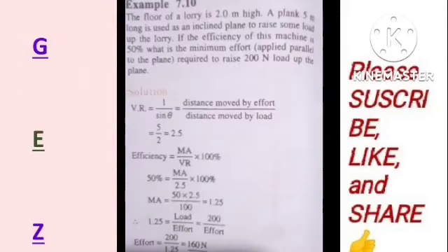Here's an example that will help us to understand this concept better. So here we have the floor of a lorry is 2 meters high. A plank 5 meters long is used as an inclined plane to raise some load up the lorry. If the efficiency of this machine is 50%, what is the minimum effort required to raise 200 newtons up the plane? So here we are still going to make use of the formula for efficiency, which is MA over VR times 100%. All we need to do is plug in the value for the mechanical advantage and velocity ratio.